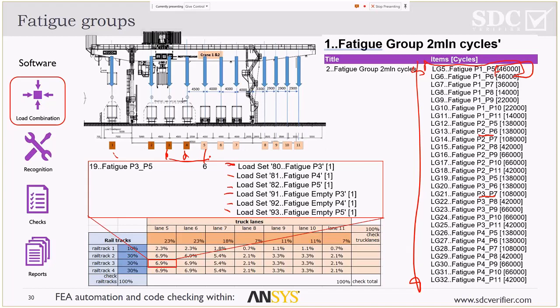So for the hotspot stress method, we recognize all the welds. We also will automatically recognize the nodes to make the hotspot interpolation figures. We are not only going to implement that, it will also be a completely automatic routine, because it is a very tedious process to make these hotspot stresses, and we can automate that completely.